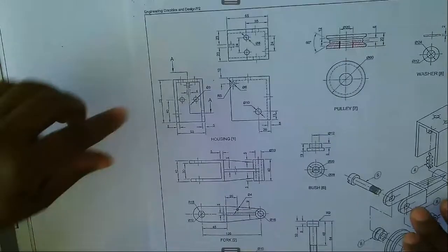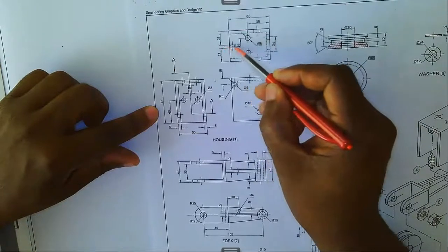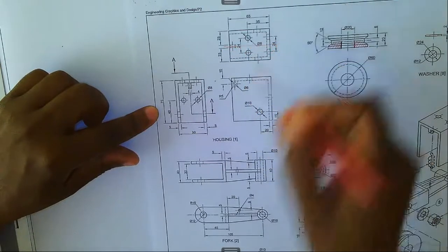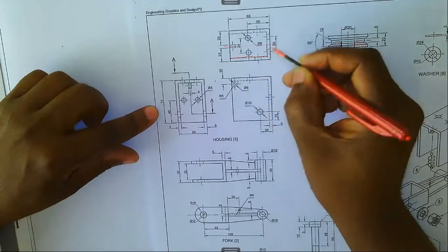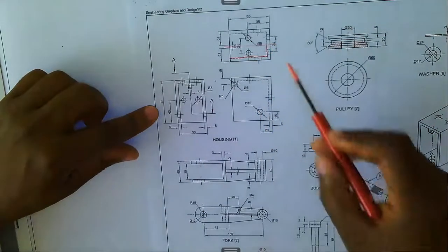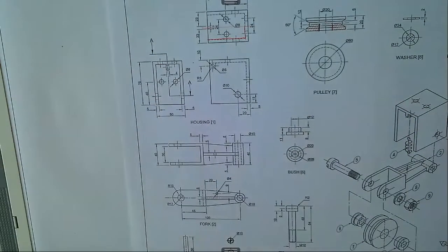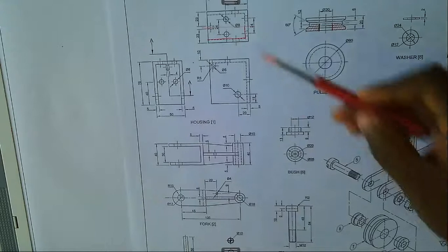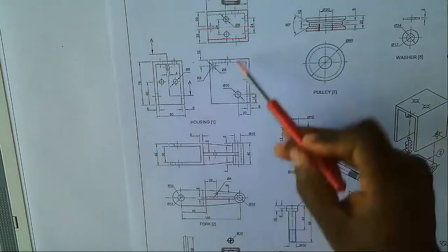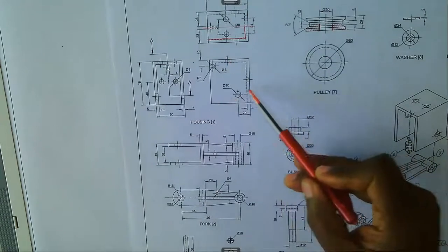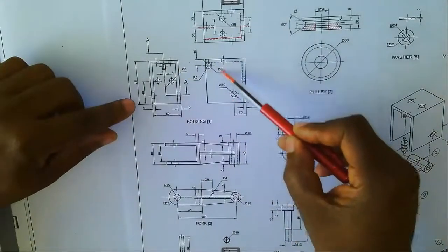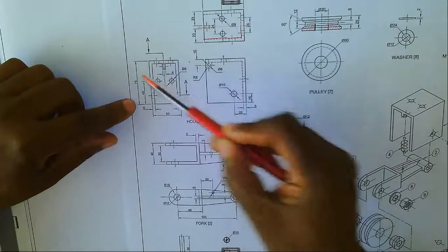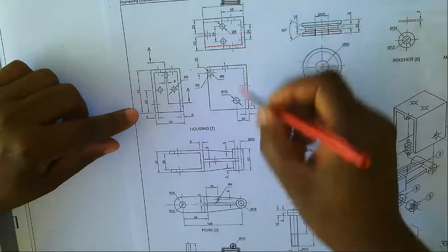Then the other thing, if we also cut here like that, remember the cutting plane would pass through here like this. So this part is going to be exposed like this up to there. But we are not going to cut through the hidden detail, because these ones are on this other side. But we are cutting through here, so we'll cut like that, and we are going to cut through this part. We are not even going to cut through this wall because this one is here and that one is there. So we are going to expose this detail, which is that.